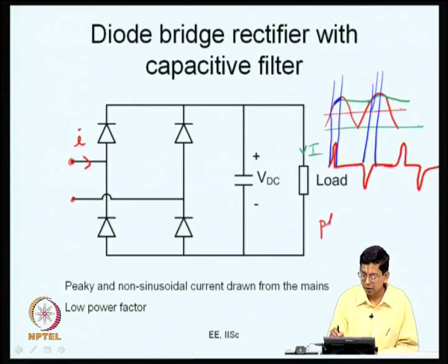This power factor is a product of what is called the distortion factor and something called the displacement factor. So, even if you have a continuous current here, if you have a highly inductive load such that the load can be replaced by a current source, the input waveform will become a square waveform. A square waveform in some sense is better than a peaky current waveform in terms of the current shape, it is probably a little closer. Nevertheless, what I am trying to say is the voltage waveform could be like this and the corresponding current waveform could be something like this. It is possible that you can come up with this in a different scenario.